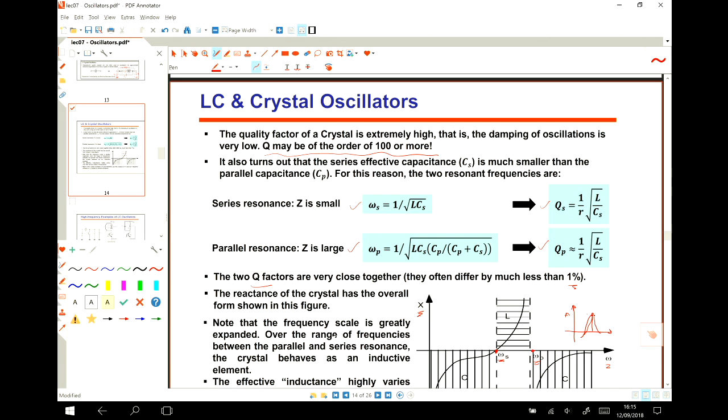So your oscillator has more bandwidth, which we are not interested in, because then, for example, if you multiply this signal as the LO to your baseband signal, then the bandwidth that you are occupying is more than the bandwidth of your baseband signal, because this one has its own bandwidth. But if it is only one single tone, then exactly the bandwidth in the RF and the bandwidth in the IF are the same, and also the recovery of the signal is much easier.